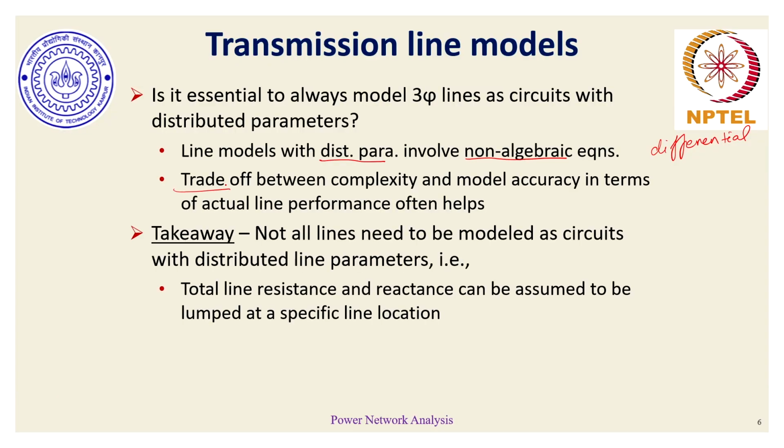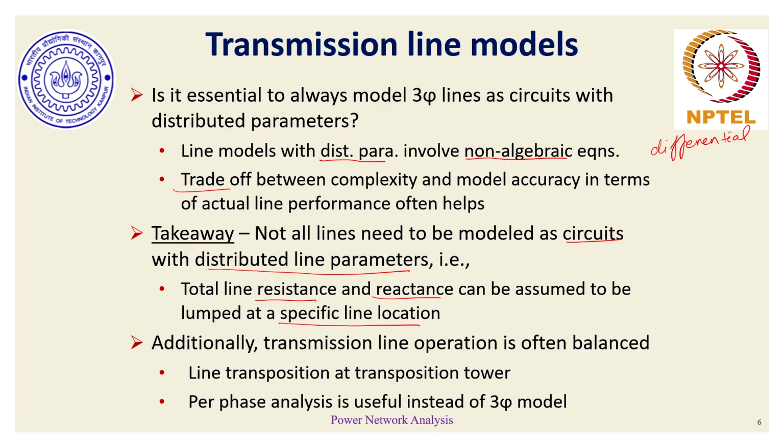So the takeaway is not all lines need to be modeled as circuits with distributed parameters. The equations that would come up need not always be differential. We can simplify our model, assume these line resistance and reactance to be lumped at a specific line location rather than being distributedly present across any section of line.